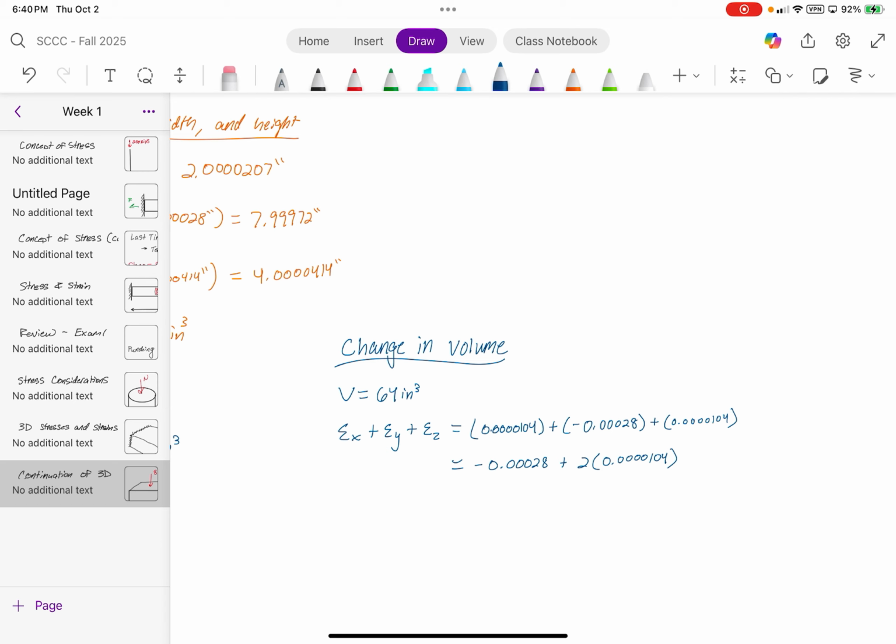Like this problem, if you're dealing with steel, you can see why the variation in change is negligible. But if you're dealing with a very soft material, like a bearing pad on a bridge for beams, that material is designed to expand accordingly, because it's supposed to be soft to relax the amount of stress that's provided on the concrete. It's supposed to distribute the force more evenly, and the only way it can do that is by expanding under load, just like this. Make sense?